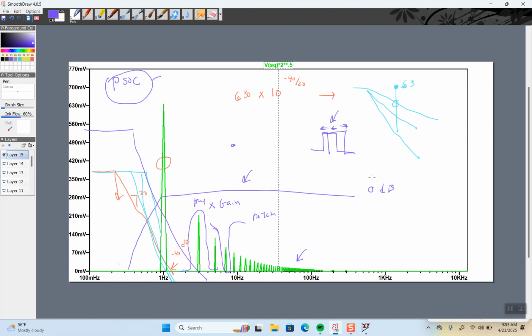We use this to know if there's a high frequency short when you're designing the ground, to make sure the current actually goes through the ground and there's not a high impedance. Make sure that your ground leads have lower impedance for the frequency. Wow, that's a great example.